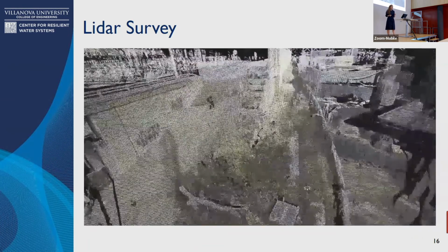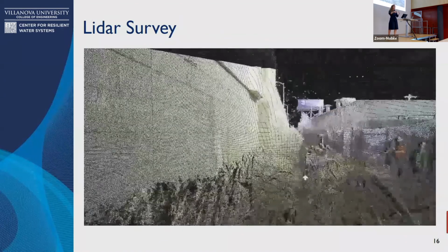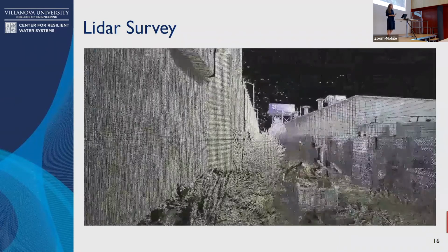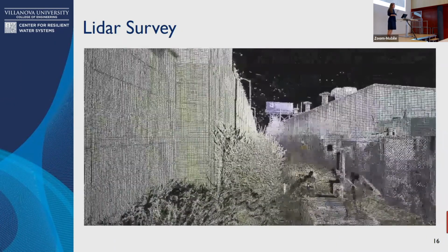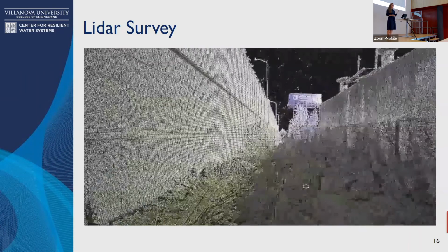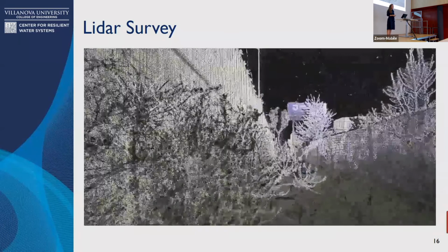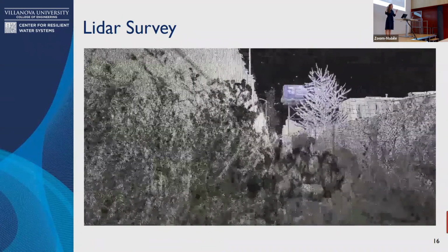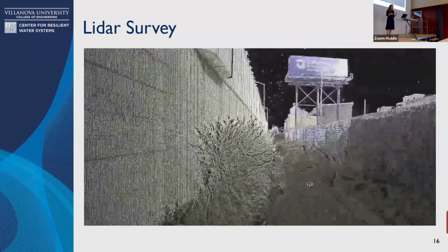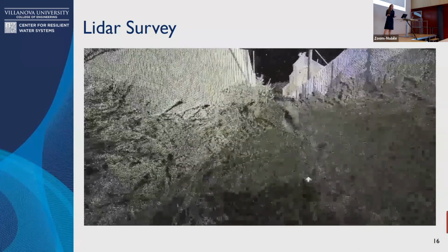And what Lidar allows us to do is we can use the reflectance, we could see where there's any topographic changes, of course. This is giving us accuracy to the millimeter level, but it's also allowing us potentially in the future to look at where clogging might be, where we're getting changes in vegetation, how much vegetation is changing season to season, because we can use the reflectance to filter out what's vegetation and what's not. So there's a lot that we can do here. And even though the rendering isn't able to keep up with the accuracy, I hope that this gives you a feel for the type of information we're able to extract from Lidar. It's kind of like you get a tour of the rain garden in 3 dimensions.